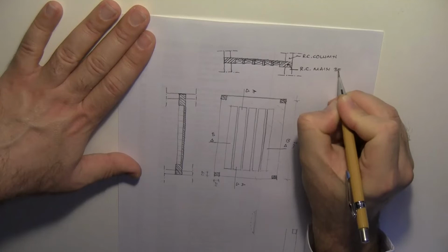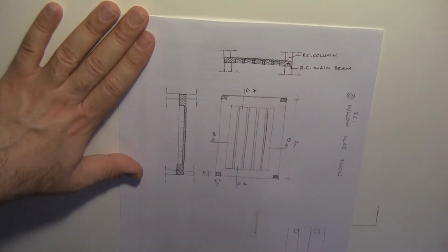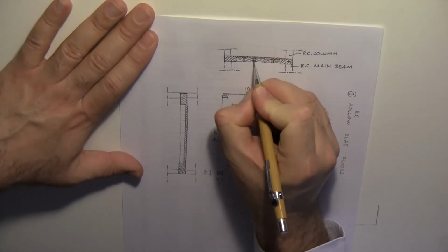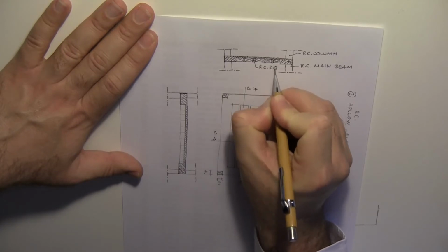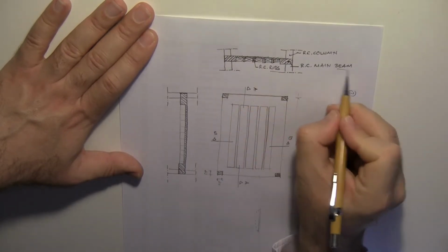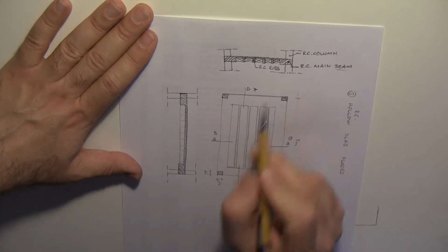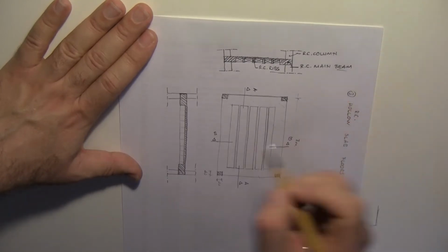When you watch the recording of the lecture, you will see that I have defined main beams as beams which connect columns to each other, and we have got reinforced concrete ribs here. Okay, and I have explained the difference between a rib and a beam. The span passing component, if it is smaller than 30 by 50, that will be called ribs. If they are 30 by 50 or more, we are going to call them beams.